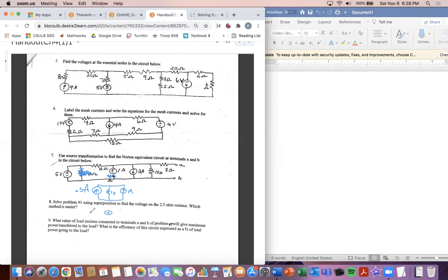So what we have here is... my bad. I kind of missed out the part where you got 0.5 amps here. Yeah. What I did is I took 5 volts and divided it by 10. Got 0.5 amps. Got you. And the 10 ohm resistor becomes in parallel because we just now made a Norton equivalent from this combination. Cool, thank you. And then we combine the 0.5 amps with this 1 amp source now, because you can combine them in parallel for source transformation.